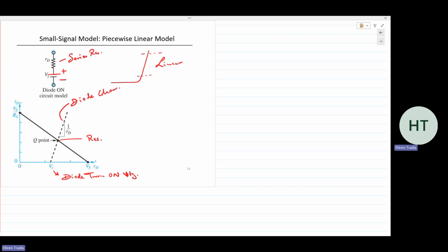In the lab, we performed the experiment lab 2, circuit number 1, where we extracted RD parameters. That is the static resistance, because it's only at one point. If it's between 2 points, then it's dynamic resistance. So in this case, you can take any 2 points, and it gives you the diode resistance between those 2 points.